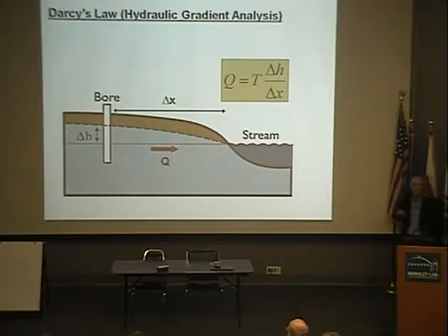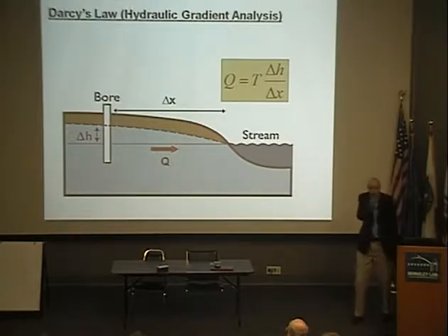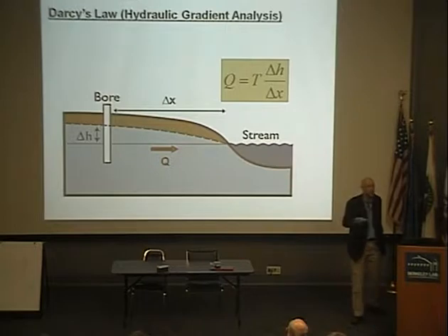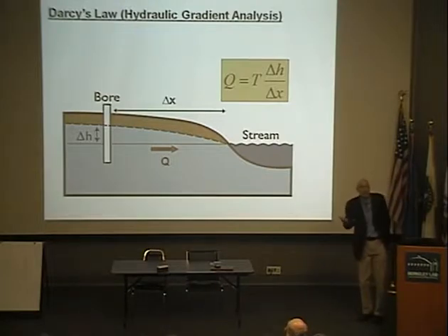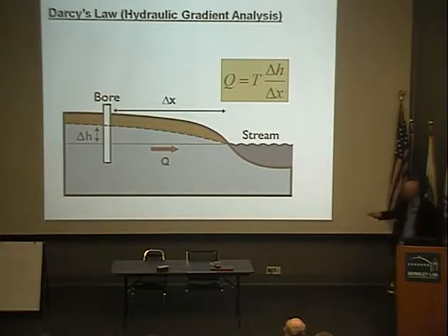And for a long time I thought, well, this is what we need to do. We need to make sure we've got groundwater bores near gauging stations to look at the exchange flux, the tendency for exchange. It turns out that would give you a very, very local measurement. Not only is there a problem, as we would all know, from measuring hydraulic conductivity to quantify the flux accurately, and the hydraulic conductivity of stream bed sediments is particularly variable.